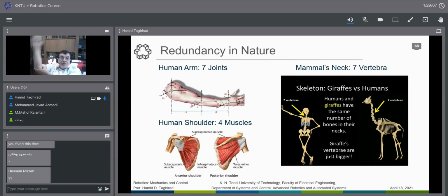And also the elongation here. Both of them are in this direction, and at the wrist we also have all 3 directions. So we can say 3, 2, 2 or 3, 1, 3. We have 7 degrees of freedom, 7 degrees of actuation. Of course, a hand needs only 3 position and 3 orientation. Why did God consider adding another actuator to the system to become redundant in nature? And we know that redundancy means the manipulability measure increases.